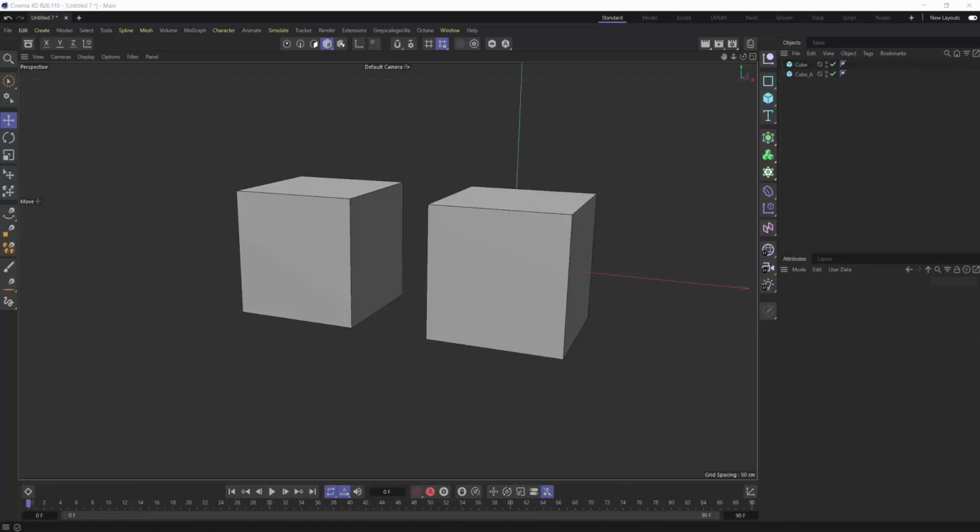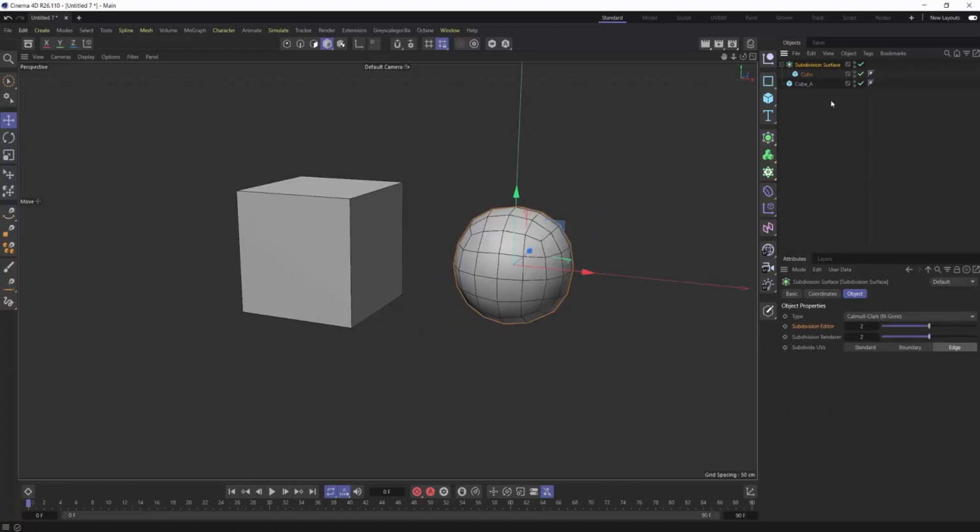With this intro to hard surface modeling, we're really going to be specifically looking at edge loops. Edge loops are what's going to give our hard surface model the quality and characteristics of that object, and with them we're going to utilize a lot of subdivision surface modeling. If I take this cube on the right and put it in a subdivision surface, it's going to turn it into a sphere, because it's looking at two or more edges and trying to round between them on all 6 sides of this cube.